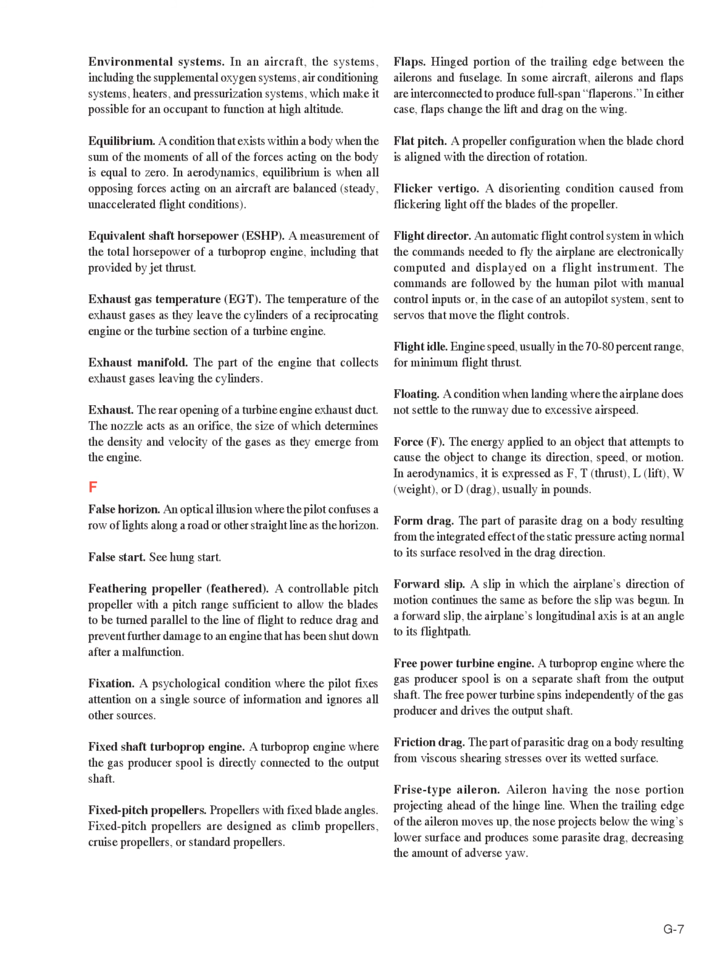Fixed pitch propellers. Propellers with fixed blade angles. Fixed pitch propellers are designed as climb propellers, cruise propellers, or standard propellers. Flight director. An automatic flight control system in which the commands needed to fly the airplane are electronically computed and displayed on a flight instrument. The commands are followed by the human pilot with manual control inputs or, in the case of an autopilot system, sent to servos that move the flight controls.